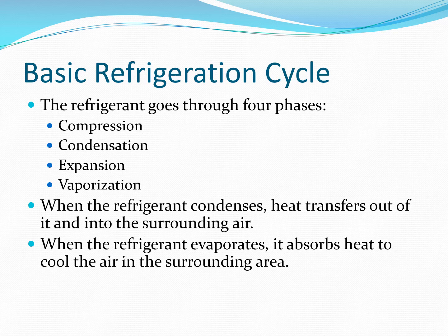Well, where'd the heat go? Well, the heat was absorbed by the refrigerant, taken to the condenser, and then it was blown off of the condenser on the outside of the house. So that is the basic refrigeration cycle. Same on the automobile as it is on your window unit air conditioner or in your central air conditioning unit in your house. Somewhere on there is going to be a condenser coil and an evaporator coil.